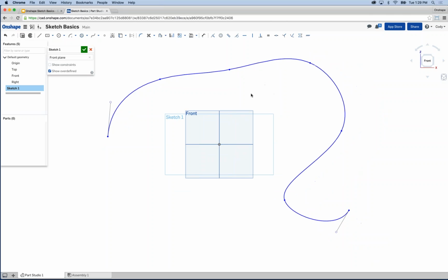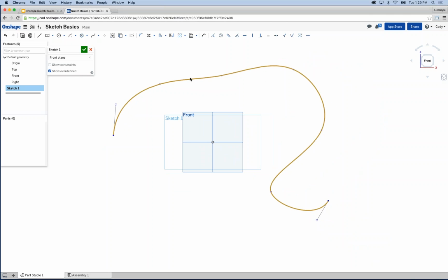Now, with the spline command, you have these points, but a question often comes up: what if I wanted to add one more point to the spline? I've already created it, I've exited the command, what options do I have? In the spline dropdown, there's a spline point command. And like the name implies, you click spline point, you move over a spline, and if you left click, you add another spline point. And this just gives you another point to control your spline.